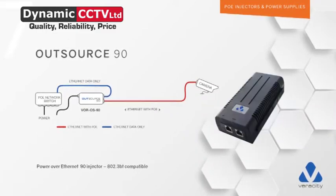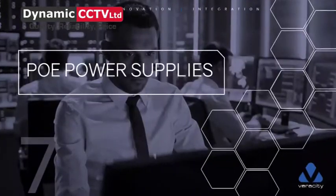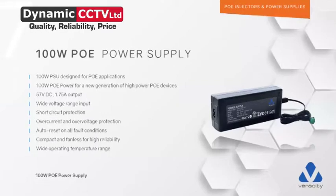This is our CEA90. This is brand new, just come out in Q4, same as the long-span Max range, which has also just come out in Q4 this year. This will give you 802.3bt compatibility. As I say, it's a 90-watt injector. That will give you, at the end device, 71.3 watts, which will do all of the bt family, PTZs, etc. So again, great device, very simple. Everything is moving in that direction, ladies and gents. If you're not looking at that type of device, you will be very soon, I can assure you, because the whole industry is moving in that direction from all the manufacturers.